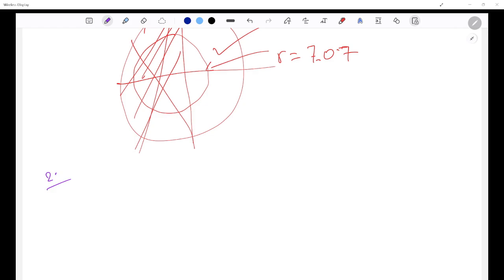Whenever we do such type of question, we should start with the unlimited workspace, then apply joint limits one by one. Don't apply all of them together, you won't be able to get the answer. If you apply the limit to joint 2 first, it won't make sense because joint 1 has not been considered yet. So first you have to see how much joint 1 spans, then move from there and apply the restriction to joint 2, then see how much it would expand even more. That is how you proceed.